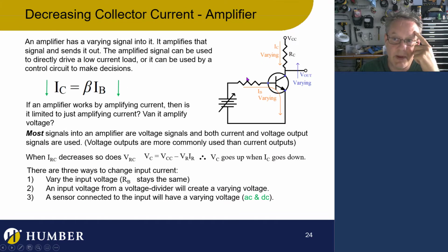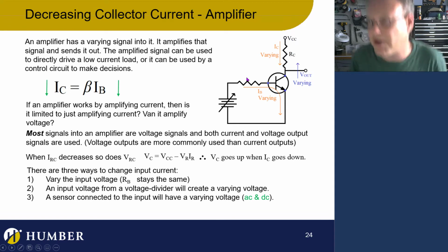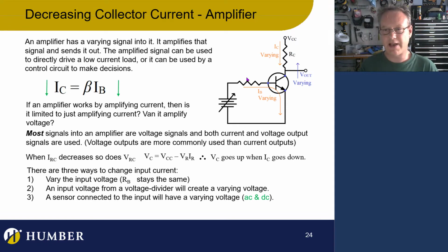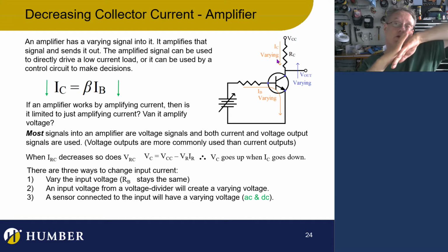This is just an example here. This is interesting. This is kind of a new example, where as opposed to turning something on and off, I'm not going to just have a load here that I'm controlling the current through. What I'm going to do is study the voltage of the collector, and I'm going to call that my voltage output. And as I vary the current going through the base, my BJT is going to be open a little bit more or closed a little bit more.